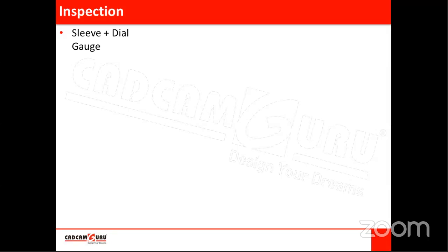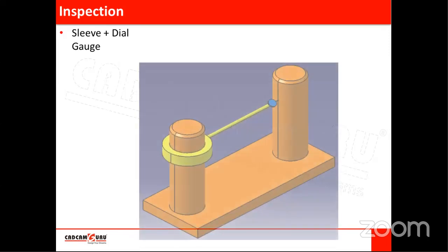Yesterday also we have discussed very cheap ways, from a cost point of view, for inspection, because inspection cost should be very low compared to the production cost. If the inspection cost is more than the production cost, it is not recommended generally. So in mass production, inspection cost should be much less than the production cost. If you want to lower the inspection cost, we should use some